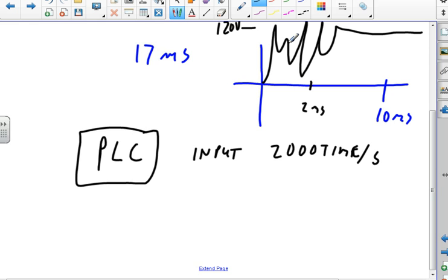If I look on page 32, I see that most of my switches are good to 10 amps, 6 amps, 2.5 amps if I'm DC. And I can take a pretty good load through those switches. So an industrial switch taking 10 amps for the whole life is a reasonable thing to do.